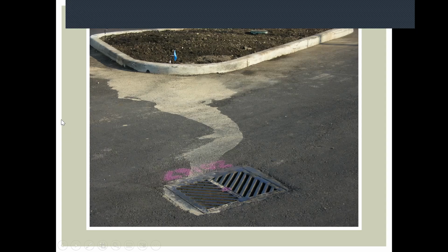And then just look for things like this and figure out what the problem is and what you can do about it. This also is a live storm system. Landscapers put in the irrigation system, tested it, and one of the pipe joints blew or something like that. And a lot of mud was washed out of the landscape island and down into the catch basin.